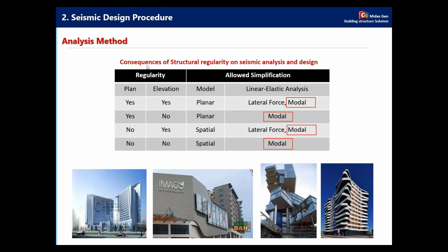When you have a building, there are some regularity requirements in Eurocode 8, and the regularity should be checked in plan and in elevation. When the building satisfies both plan and elevation regularity, you can use both methods without any problem, and both of them are linear elastic methods. You can use the lateral force method and the modal response method, that is, response spectrum analysis.